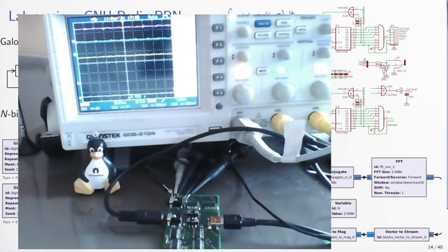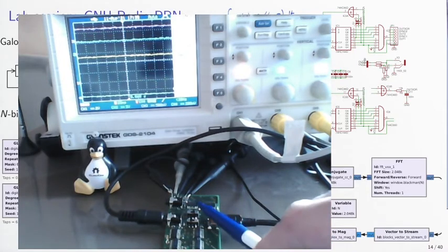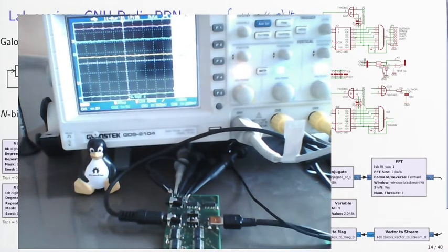So here is our implementation of a circuit. You see here one circuit with the feedback shift register. The shift register here is the XOR. This is duplicated. Here we have a switch that allows us to select one or the other sequence, and then we have here the XOR output with its low-pass filter that will allow us to detect the correlation.